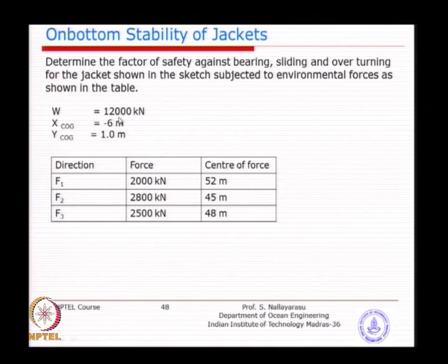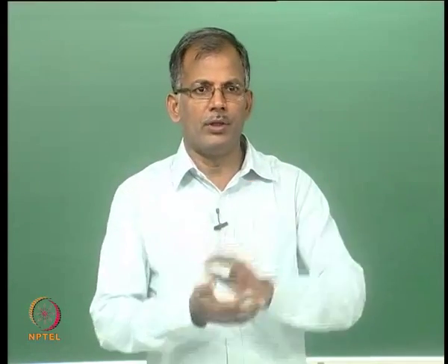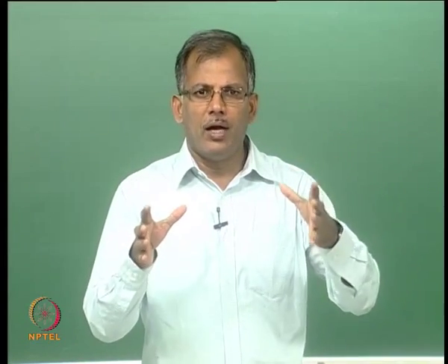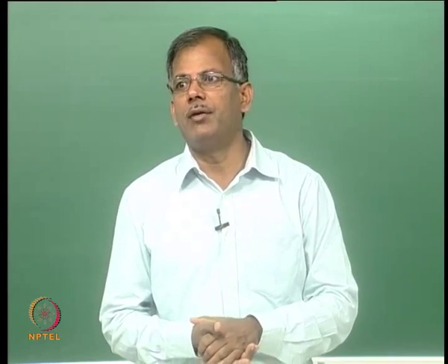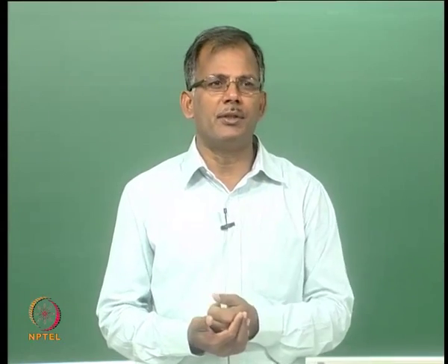And you see here the jacket weight is 12,000 kilonewton. This is the typical case. Most of the cases, if you have a 2000 tons weight of the jacket in air during transportation or load out, you will see that the weight of the jacket at the time of placement inside water will be about 50%, sometimes less than 50%.